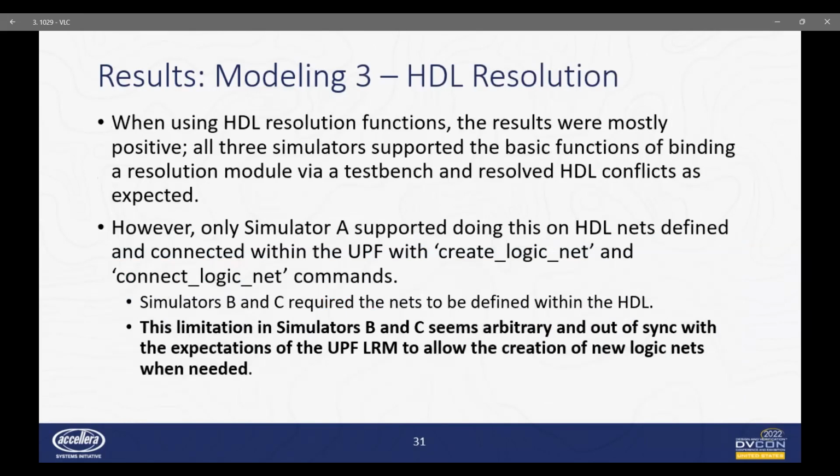The third and final approach, using HDL resolution to resolve supply nets, was more well supported. However, there were some unexpected limitations. Only Simulator A supported HDL resolution on nets defined and connected within the UPF using create_logic_net and connect_logic_net UPF commands. Simulators B and C required the HDL nets to already exist within the HDL definition. This limitation seems out of sync with the UPF LRM, and the need to modify the source HDL limits the usefulness of this approach for verification.